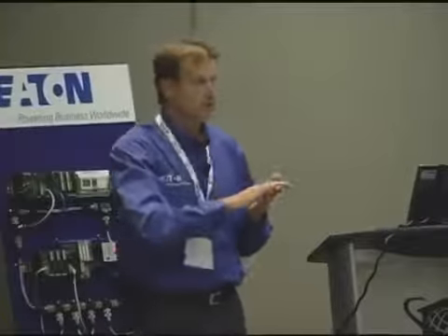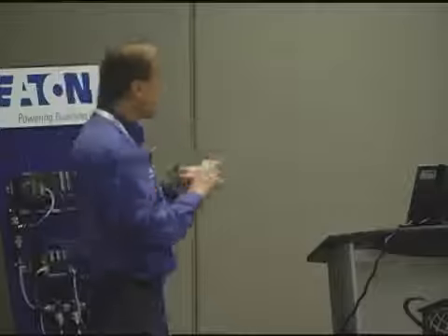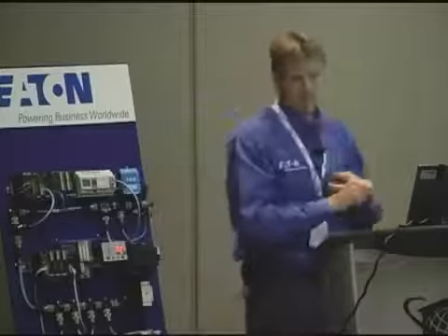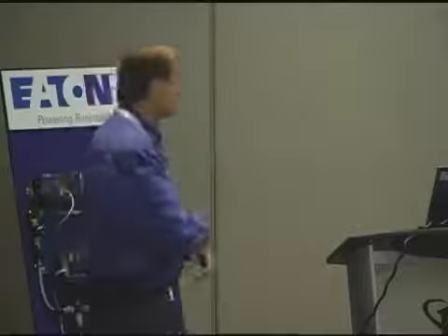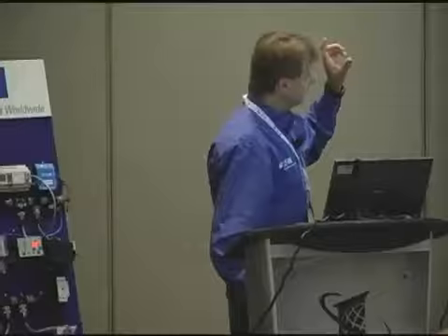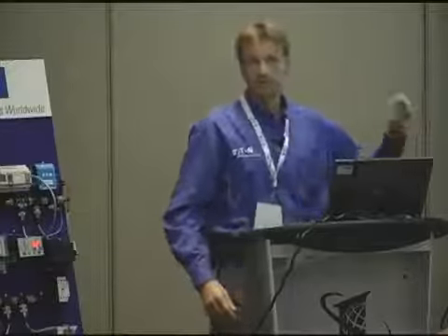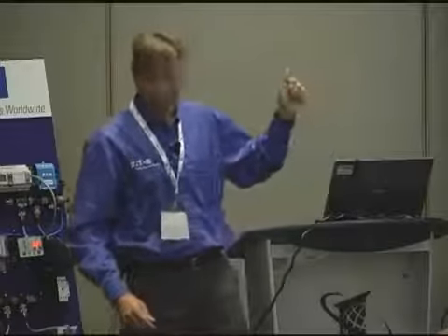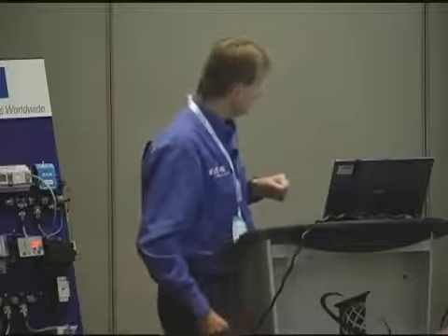And what happens is, if you have a lot of capacitance on the cable, it really limits the length of your network. And if it's too high, you can actually get communication errors. Because is that really a 1 or is that a 0? We're not sure. It's ringing. It's no longer a square wave. You kind of got some other stuff on top of that. So typically, a protocol will specify what cable to use, and it typically will be a low capacitance cable.